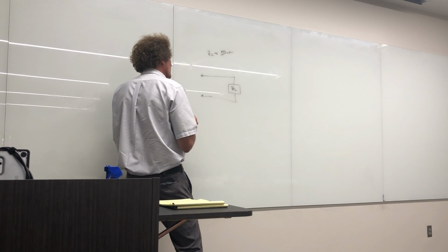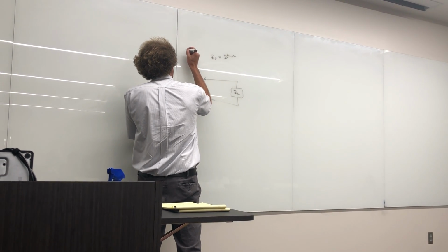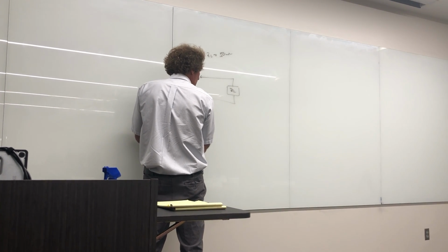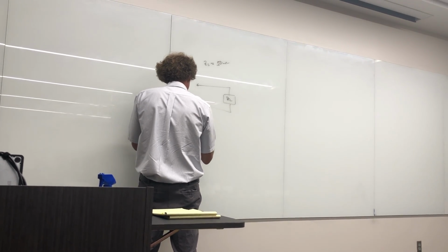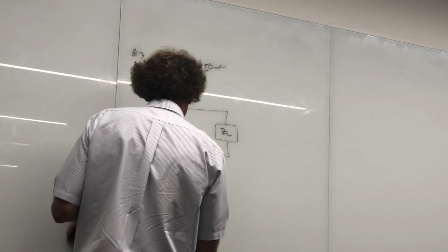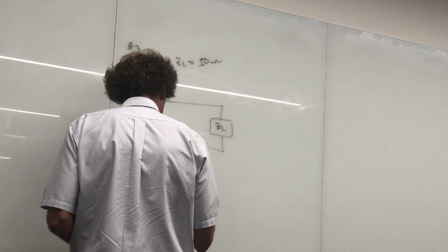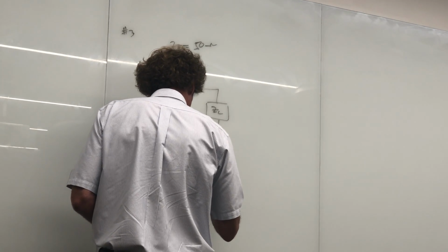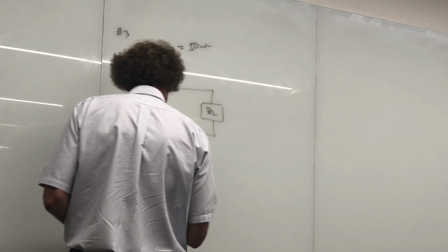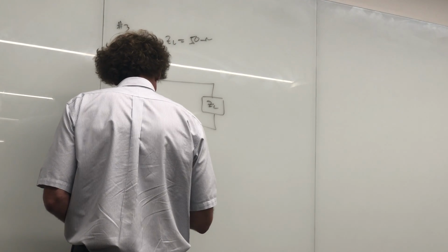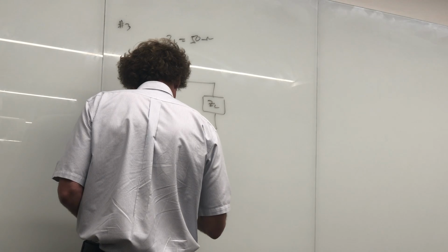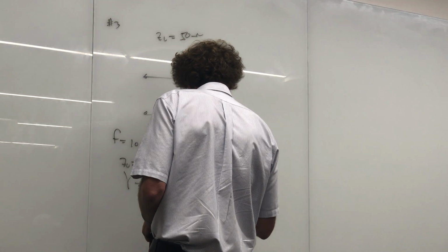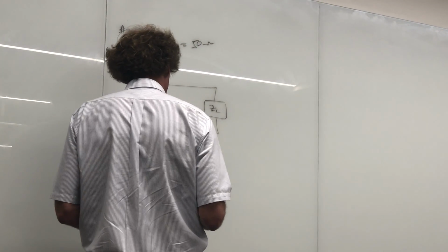Help me understand the problem. Which problem is it, for instance? It's number 3. Go ahead and read it from the beginning. It says the impedance and propagation constant at 100 megahertz for a T-line are determined to be Z0 equals 18.6 minus j0.253 ohms, and the propagation constant equals 0.638 plus j4.68. Go ahead and calculate the per unit length parameters.